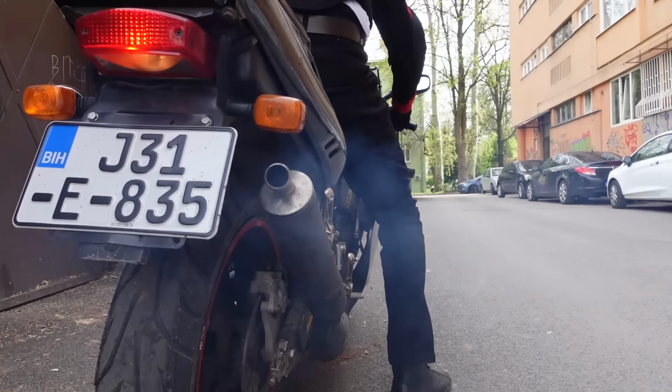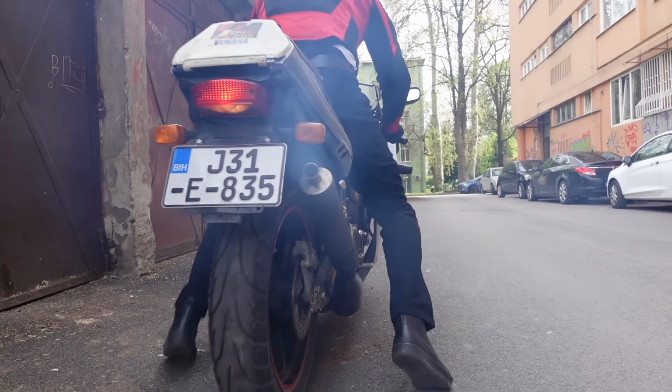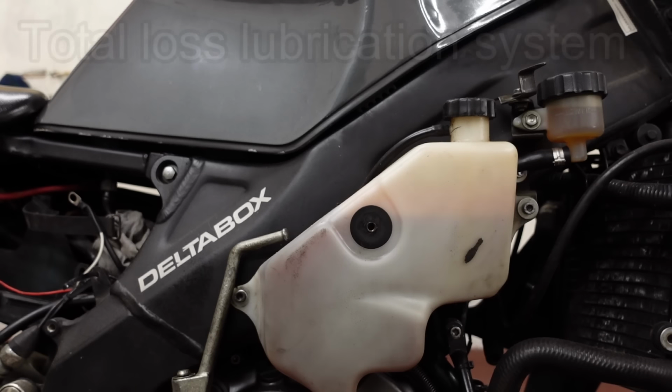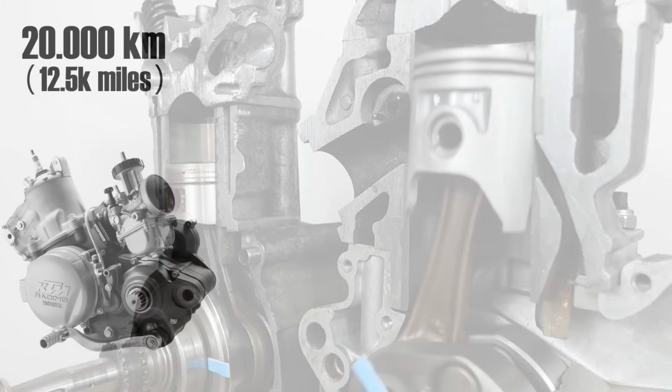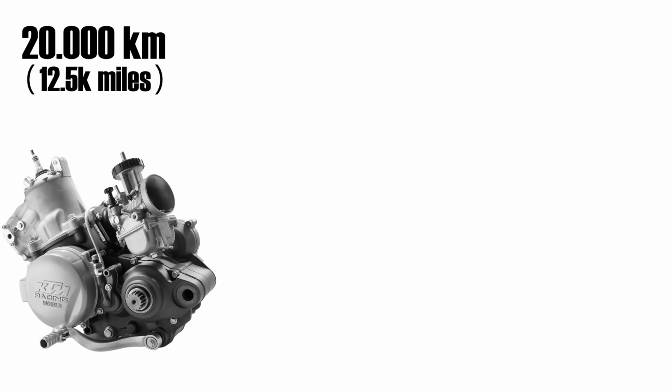This is also why the lubrication system of 2-stroke engines is known as a total loss lubrication system. The oil never gets replaced like in a 4-stroke. Instead, it's lost and topped up as necessary. This means that the lubrication of the rotating assembly of a 2-stroke isn't nearly as consistent or reliable as in a 4-stroke engine, which ultimately leads to a significantly shorter maximum potential lifespan for a 2-stroke. No amount of maintenance or lubrication quality can overcome this inherent design constraint, and the average lifespan of a 2-stroke engine on a motorcycle is somewhere around 15 to 20,000 kilometers.